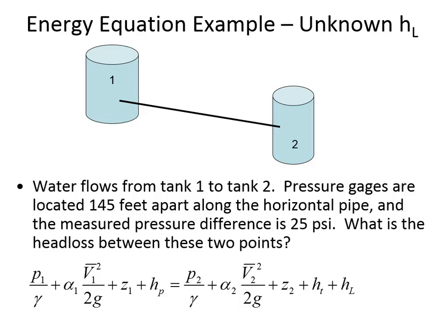And what's the significance of that? Well, if we had piezometers connected at the 2 points so that pressure was measured as some elevation rise of water, then the difference in the water elevations would be that 57.7 feet. That's how the pressure head would manifest itself. As the flow is continuing at a consistent flow rate, the velocity isn't changing as friction robs the flow of energy, but pressure is decreasing, and so pressure head is decreasing.